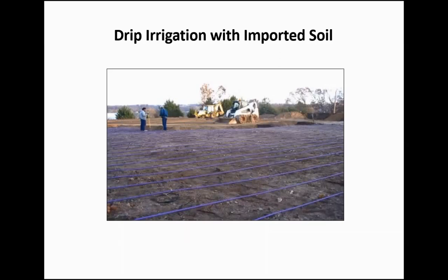such as a good vegetative cover and regular monitoring of the dispersal and aeration components. Backflushing of the tubing is necessary to clear out solids deposited in the lines. And also pressure release valves may be necessary to lessen freezing and infiltration of soil in the drip emitters.